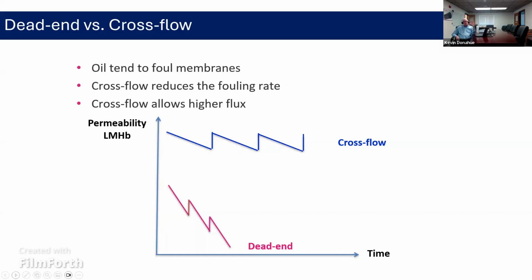And in this case, the ceramic membrane is like a safety filter. It's not a heavy duty separation needed. So a dead end filter is perfectly suitable for that case. But for heavy oil and grease or large amounts of suspended solids, the cross flow mode is really necessary to make this technology practical.